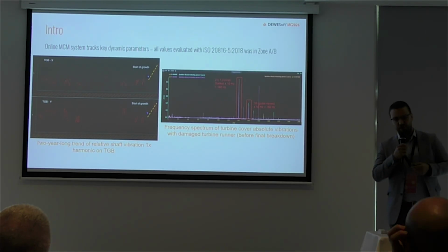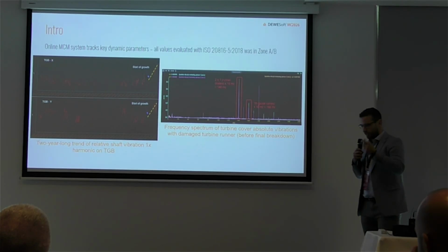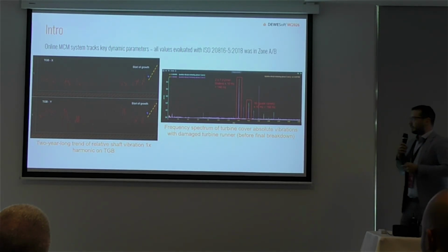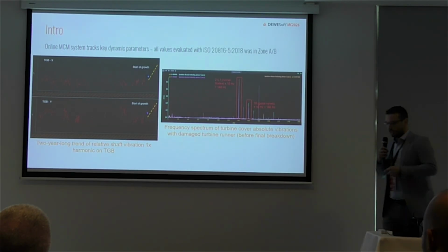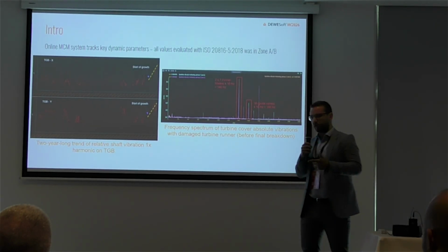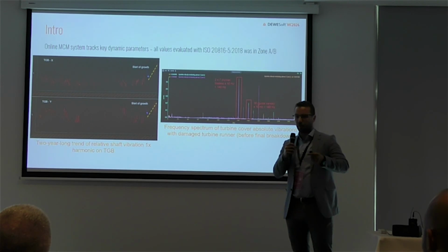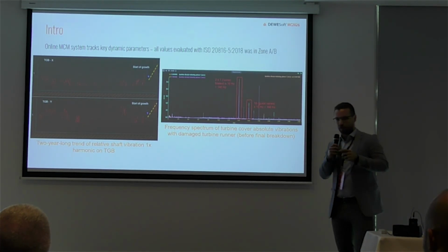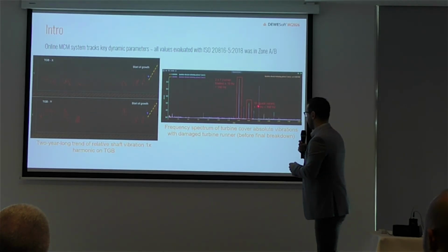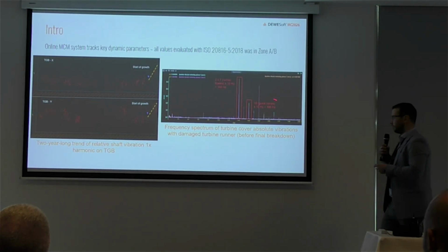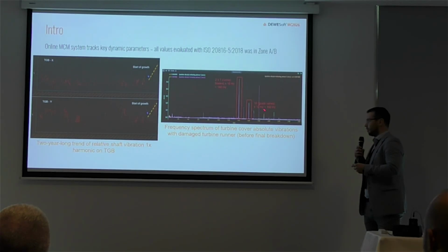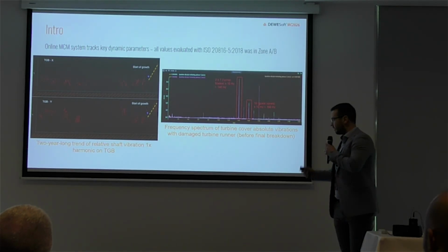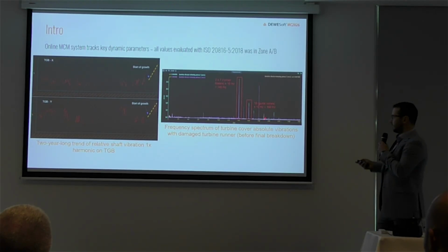Since I already explained, we have the data for, I don't know, 10 years before that, and when we look at the spectrum of the relative vibration and absolute vibration, which we measured on the turbine cover, we found out that at some point, for example 2 years before the complete damage, there was the 16th harmonic of the nominal speed, so 160 Hertz. A component occurred.